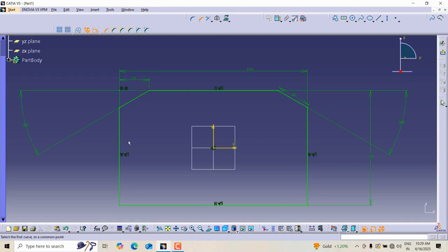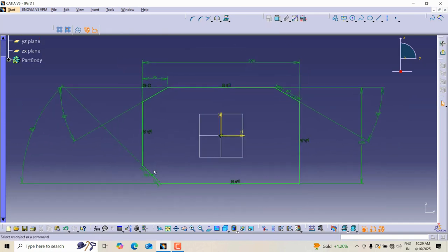And the last one, select the corner, drag it here. Now see, we have not provided the type of chamfer required, so it is taking hypotenuse by default. After selecting the corners, don't click directly. Select the type of chamfer first and then go for the corner treatment.